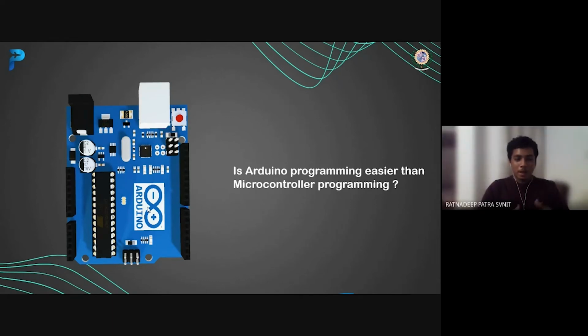Yeah. So as you can directly see in this image also, the main processing unit of this Arduino is just the ATmega328P. It is the main microcontroller, the main processing unit that is performing all of the tasks. But apart from that, the Arduino board also consists of several other things, like this DC power supply that you mentioned, or we can directly program using the USB, or there are some other integrated chips that allow us to use these analog pins as digital pins as well. This flexibility is all provided by this PCB design, using these integrated circuits that are attached to it. Due to this flexibility, Arduino coding is a lot easier. And as you also mentioned, in the Arduino IDE we have many predefined functions, so we do not have to write the code from scratch. While programming any other microcontroller, we need to know its architecture and we have to write the code from scratch. That is not the case with Arduino.